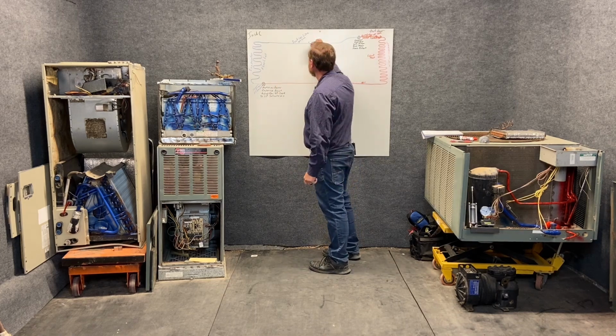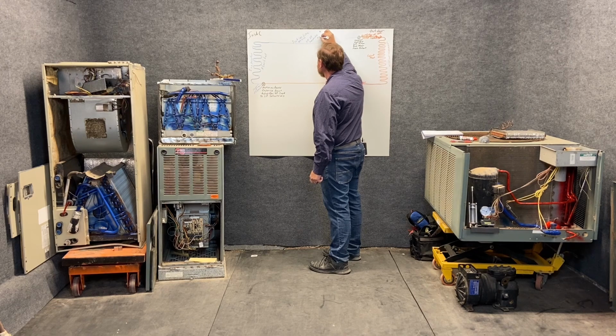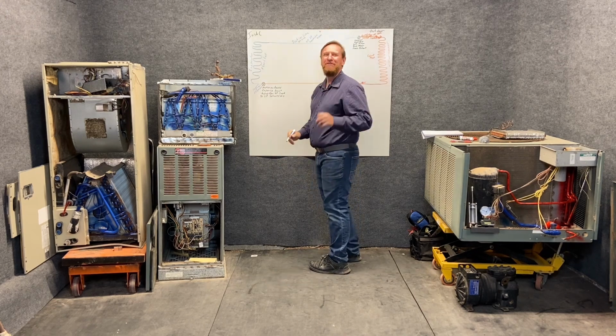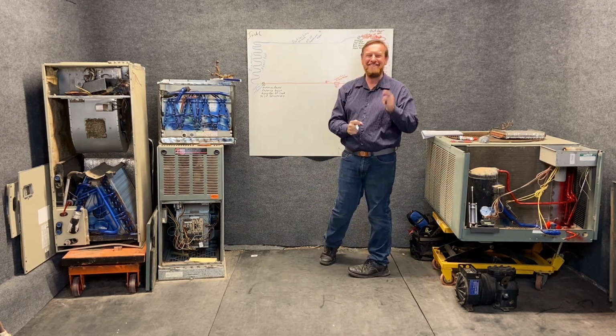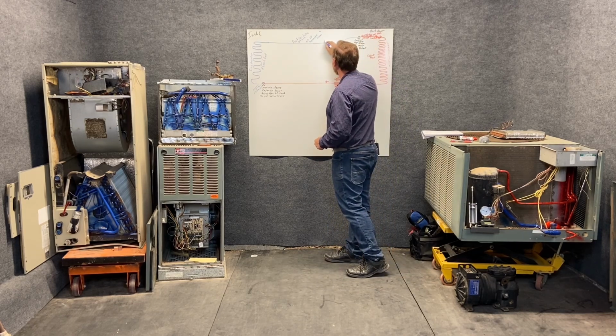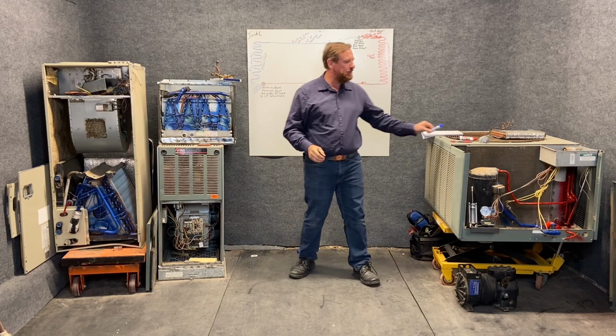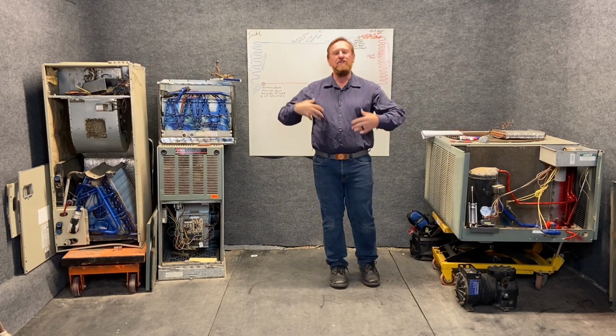The state of refrigerant in this line is extremely important. It is a low pressure, LP, low temperature, LT, superheated vapor. We're going to talk about that superheated vapor later. You're going to have to hang on because I'm not telling you just yet. It's a low temperature, low pressure superheated vapor. And what we're going to do is put our little arrows on here so that we know we now have a full and complete cycle. It's very important you put all of those words together.